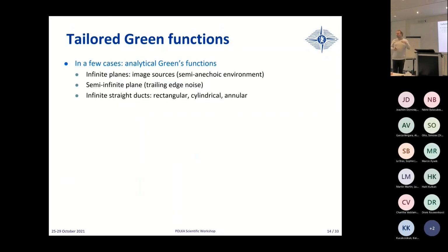So if you have an airfoil, and some turbulence that develops over the airfoil and is passing in the vicinity of the trailing edge, your Reynolds stresses in here, the rho 0 Vi Vj, that you need to scatter by the geometry,